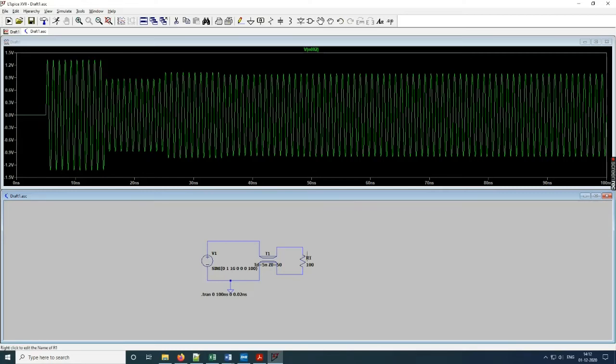But just after 5 nanoseconds, the wave hits the load and starts to undergo reflection. Now the reflection coefficient is something that you can easily calculate, that is (ZL minus Z0) by (ZL plus Z0). So what we are seeing after 5 nanoseconds until about 15 nanoseconds is the superimposed voltage arriving as a result of two waves. One is the forward wave, the other is the reverse wave.